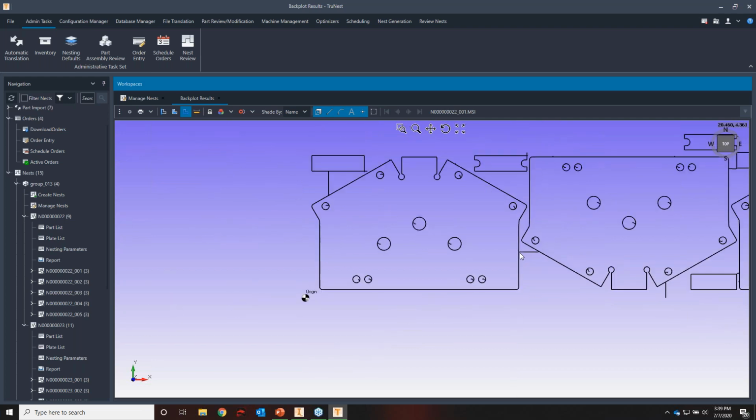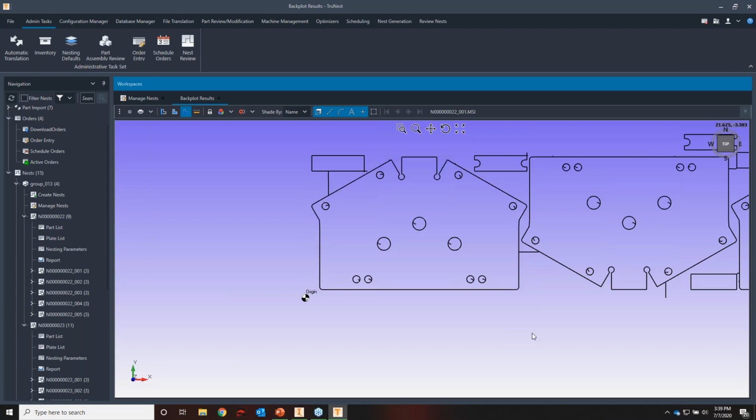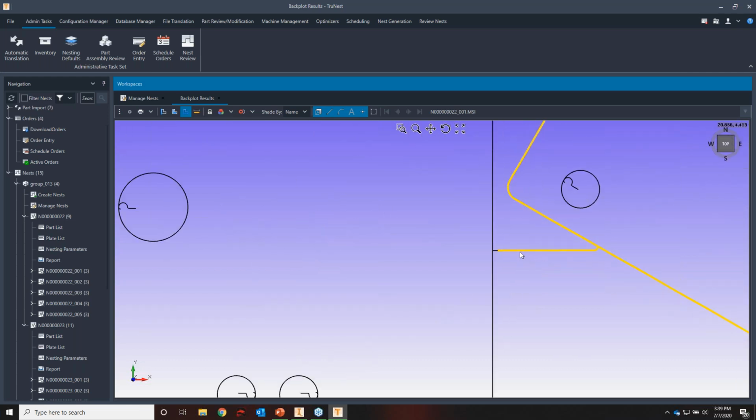That's so that we make sure the quality of the parts is not sacrificed when we're cutting these out. If this happened to be on the other side, this part could end up snapping back due to the internal stresses of the material, and end up getting ruined just from having this lead on the other side of the particular piece of geometry.